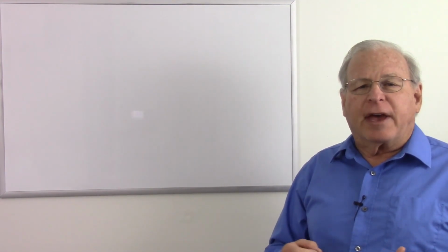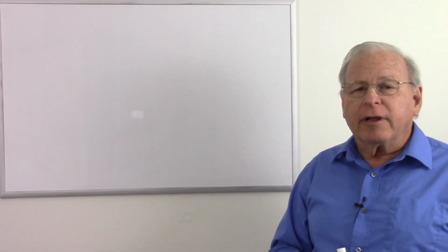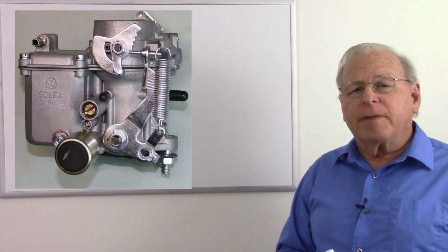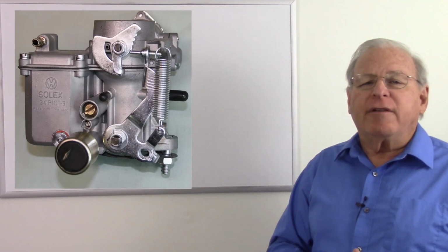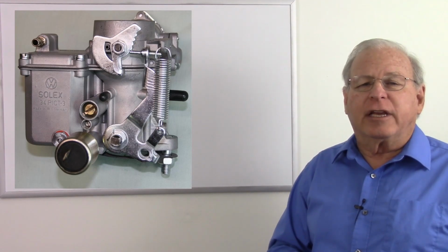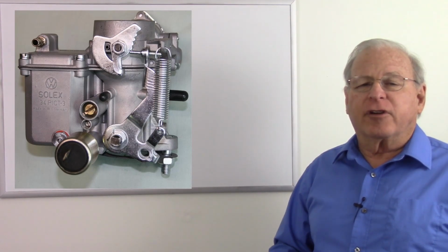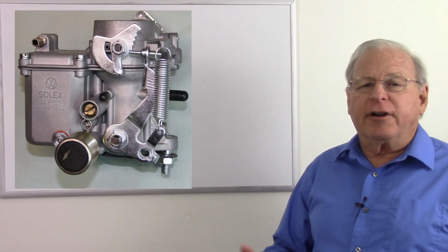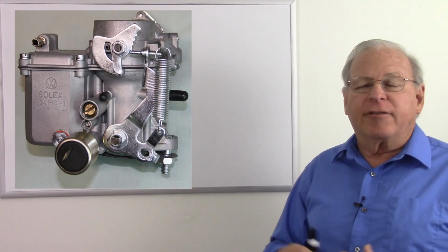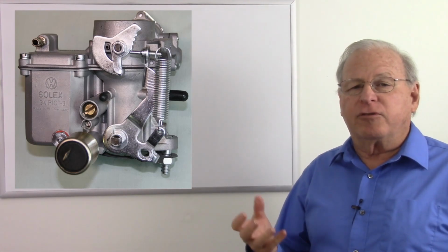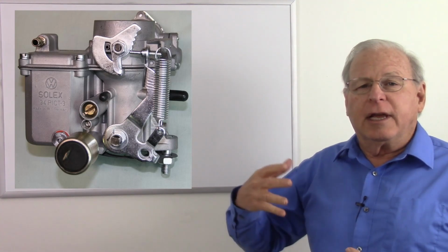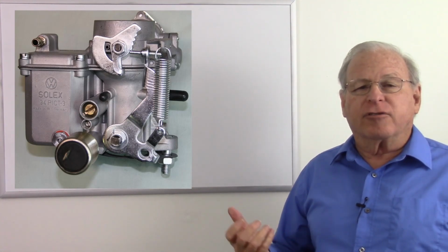A newer type of analog computer is a carburetor. This is something you may have dealt with yourself. A carburetor has to deliver the right fuel-air mixture to a gasoline engine under varying conditions, under different throttle settings, under different amounts of airflow, and sometimes even a different temperature when it comes to choking the system so it has a richer mixture when the engine is cold.